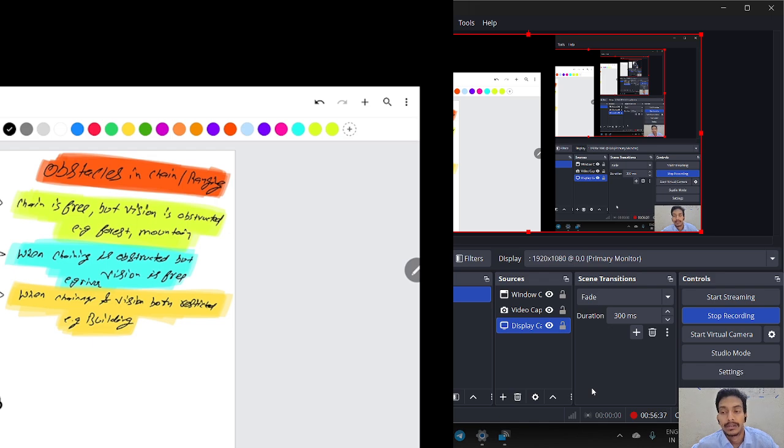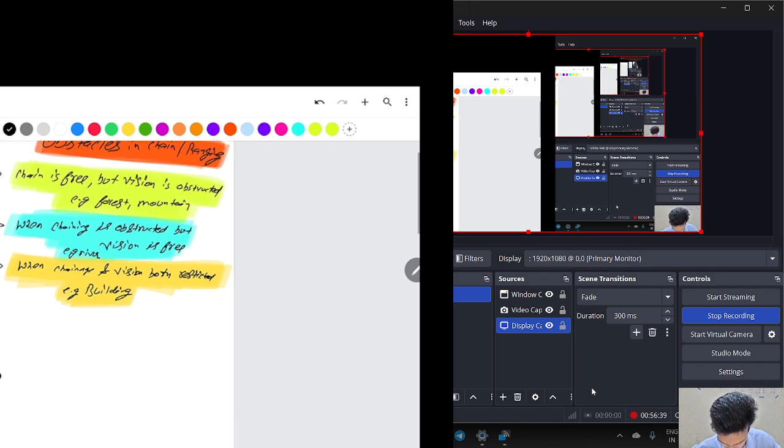That's why the chain is obstructed, like a river. We can see the river here and there, but we can't use a chain. We have to do offset of perpendicular, or we take an equilateral triangle or hypotenuse.